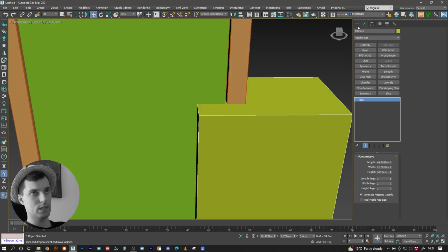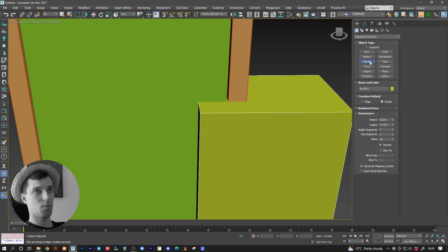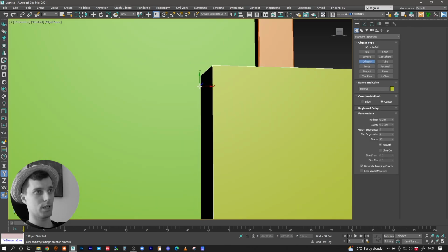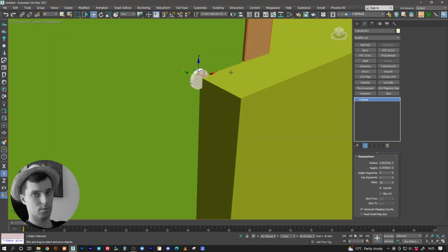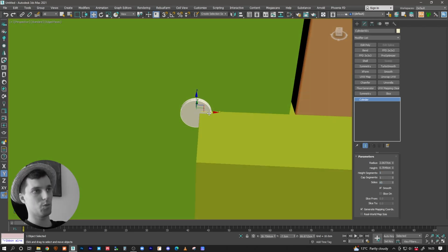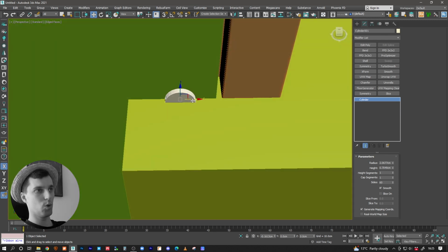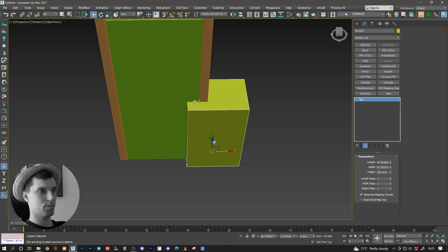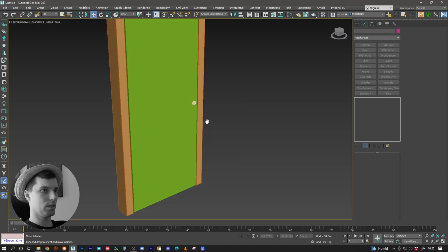The door handle obviously depends on what the handle is, but let's just talk standard sizes. Let's model a cylinder, press auto grid, and put something like this. This is, by the way, a simple primitive door. Put one segment here, maybe 60 there, because you might be standing close, and I think 60 is more than enough. I wouldn't apply any turbo smooth modifiers for now. Let's centralize this and delete the door for now.